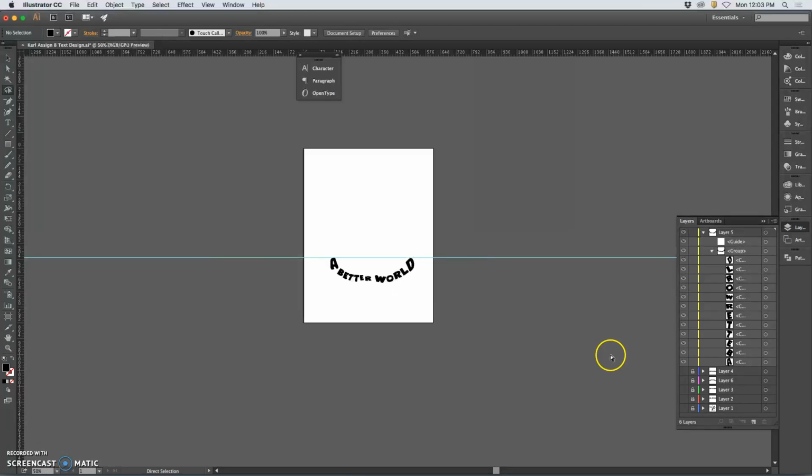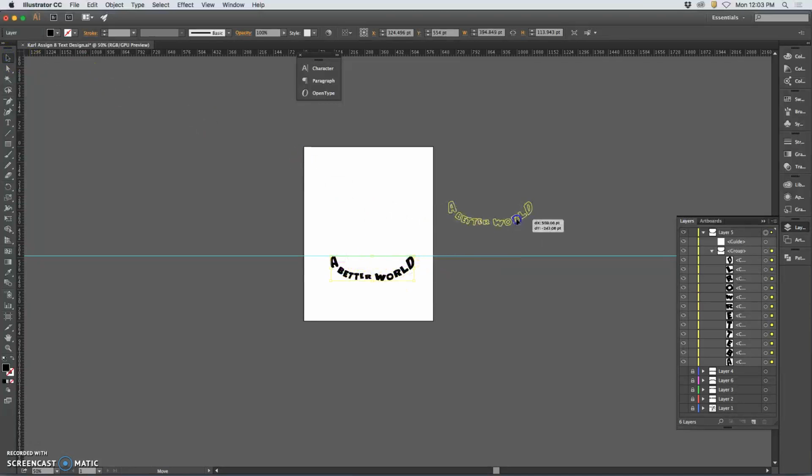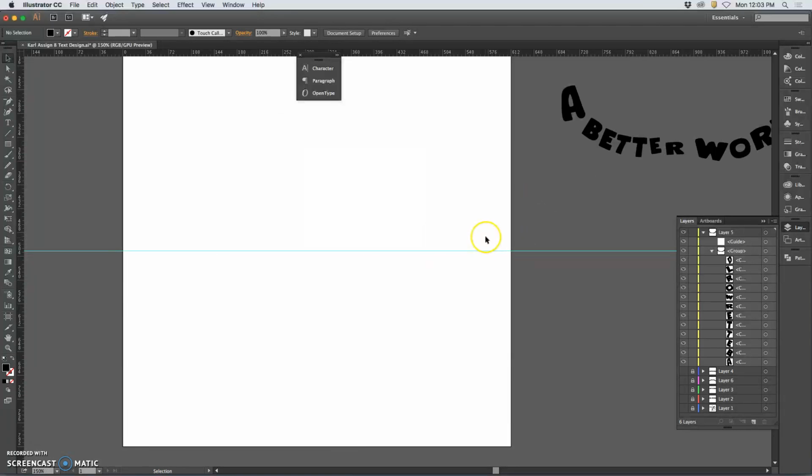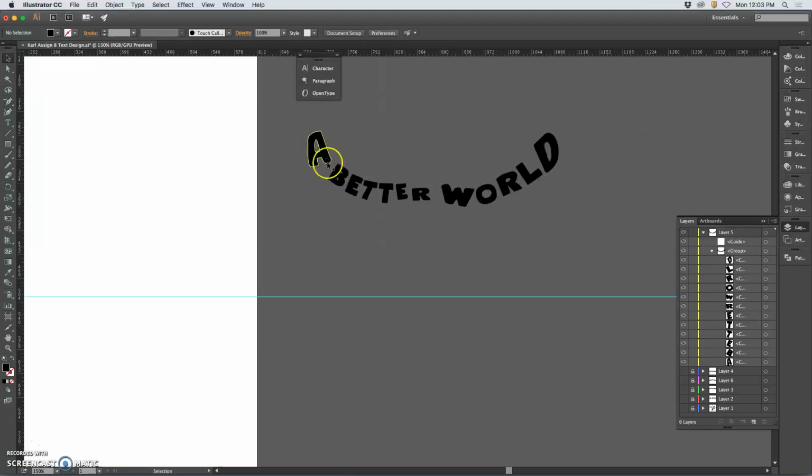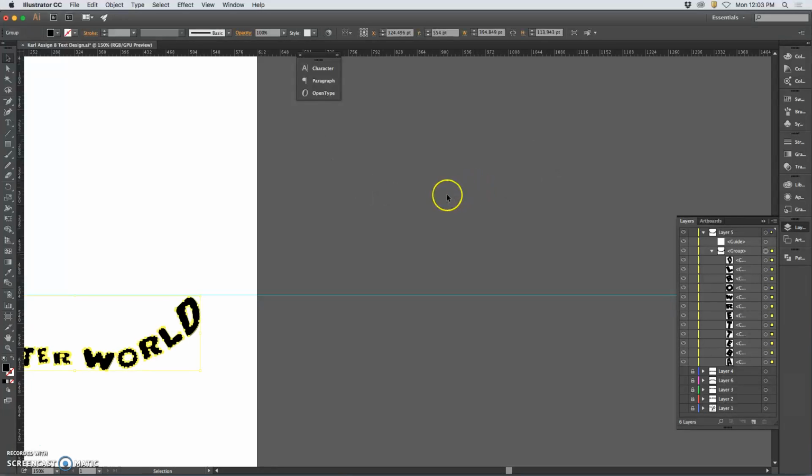Right. And notice I don't have any white in it at all. It's not a bad idea to check that. Select it all, move it off of the white artboard, and make sure there's no white in the design. If there is white in the design, because you used white shapes to kind of erase away, looks like a Cheshire cat grin, I like that, then you need to select both shapes and use the white to cut out from the black using the Pathfinder exclude function. But if it does look like this, then you're in good shape.